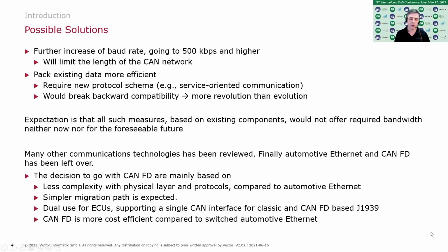And the other thing that we really looked at is packing the existing data more efficiently. Whenever we tried this approach, we figured out that based on the existing parameter group definitions, this is not so easy. And at the end of the day, it would require a new protocol scheme. So we probably would have to switch over from the all broadcast communication scheme that we do today to a more service-oriented communication, so that we have only on the network the information available that is necessary for this particular requirement, for this particular application.